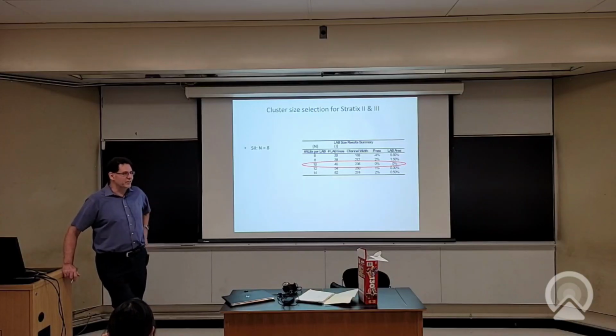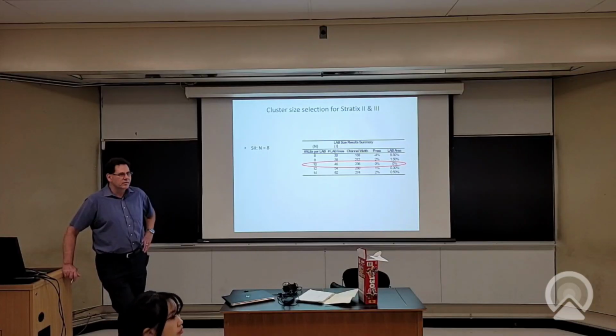That's effectively the trade-off. Then it seems like you're not able to use the LUTs if you have some specific logic, like that specific logic block. If you use these extra boxes and routing ports, now you use up the routing ports where maybe you could try to pack another logic with that LUT after you put something else. Yeah.